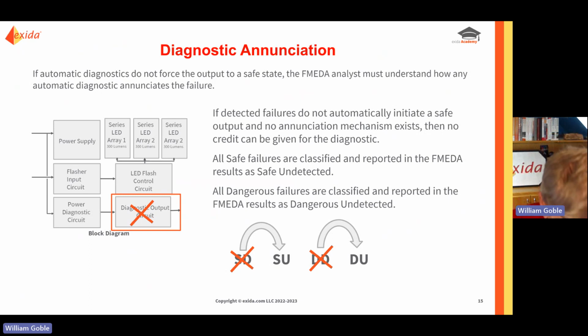The probability of human error, especially in low safety culture installations, is really high. And so we've chosen not to give any diagnostic enunciation credit for anything that doesn't have an automatic electronic signaling back to the maintenance station or automatically shuts down.